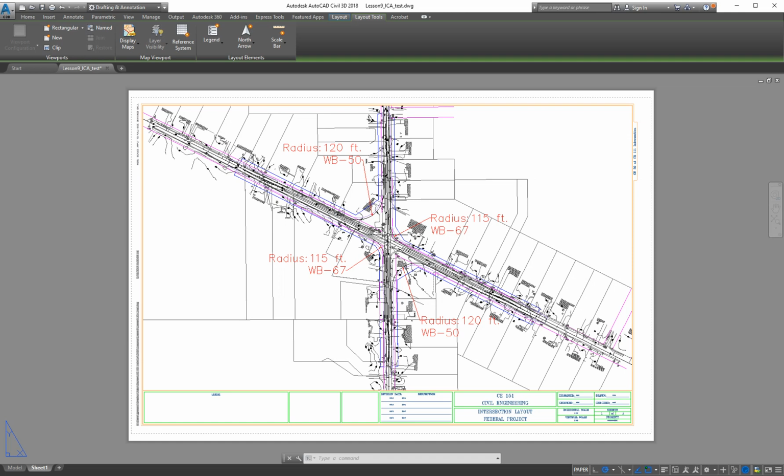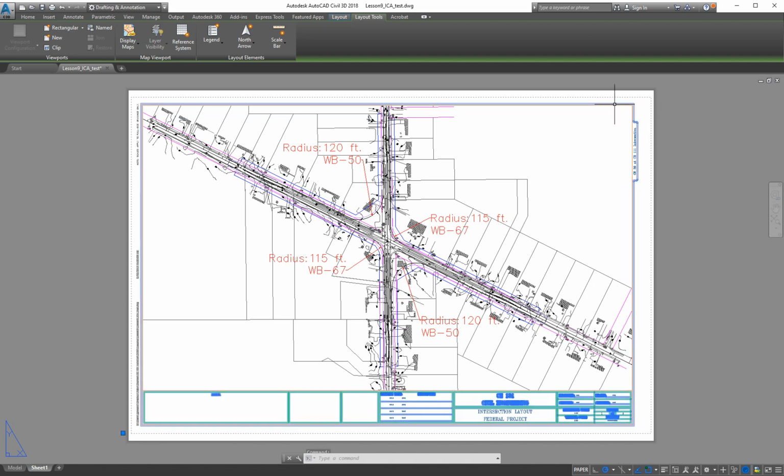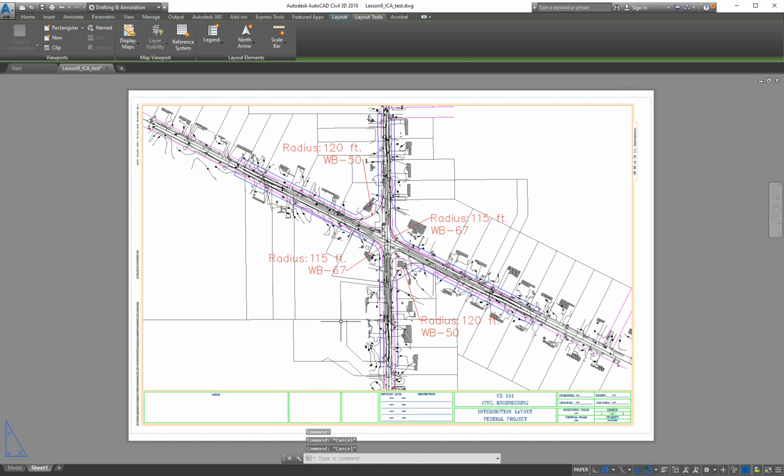This is a picture. The way we like to look at it is we create these windows, we call them a viewport, and you look through that window into the real world. You're inside the house, the paper is the wall, and you've got a window. Here's our window, and we're looking out the window into the real world. What we see is model space. So we're inside in paper space, we look through a viewport and we see the model in the real world, the model space piece. That's one way to look at that.